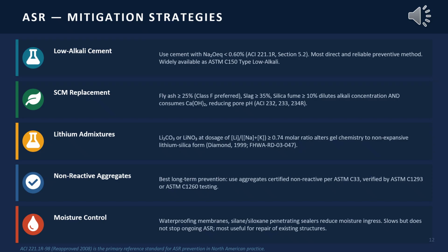The fourth and best long-term approach is simply specifying non-reactive aggregates certified by ASTM C33 as non-reactive by C1293 or C1260 testing. This eliminates the problem at source.